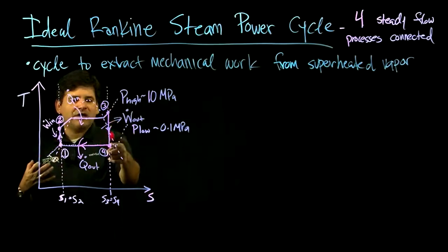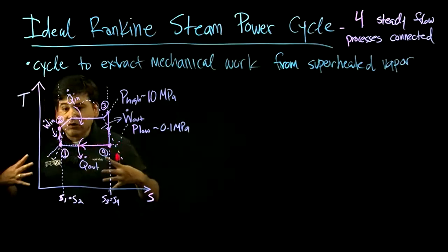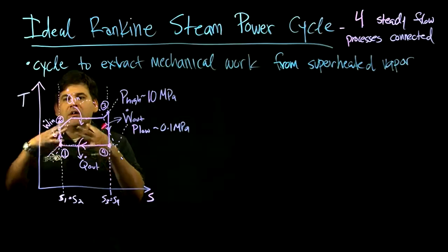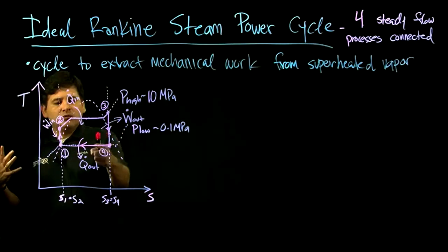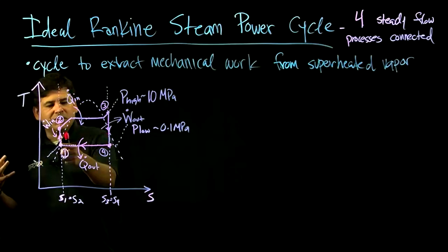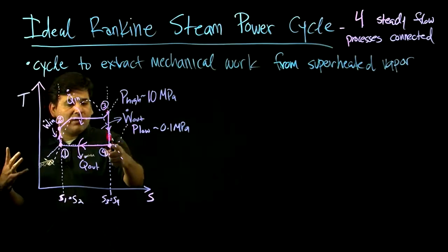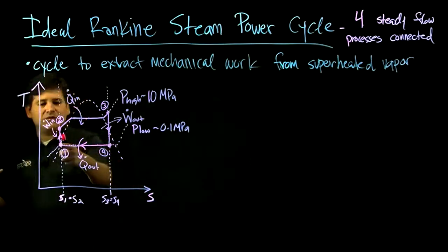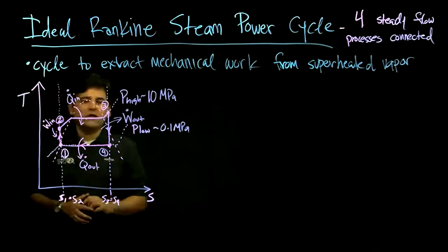The water comes out of the turbine, but to bring that working fluid water back to the original state, you expose it to another heat exchanger, typically a cooling tower, where that water loses more energy to go back to saturated liquid from close to being a vapor. It's somewhere in the mixture region, but it's mostly gas. Then you go back to saturated liquid by heat transfer out.